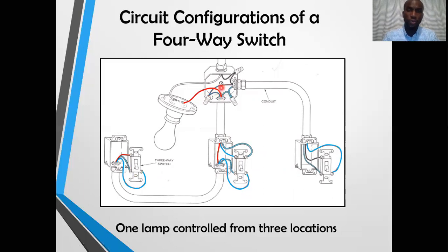Well, of course, you know that our keyless receptacle or lamp only uses switch feed and neutral, and the neutral comes directly from the source. Keep in mind that the neutral wire never interferes in the control process, because the purpose of the neutral wire is to form a return path for current to flow. So the current enters the circuit on the black wire and goes back to the circuit breaker on the neutral wire, which makes the circuit complete.